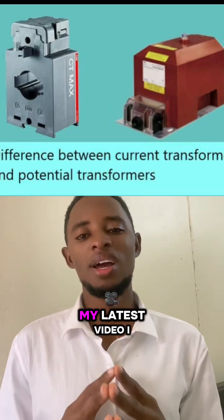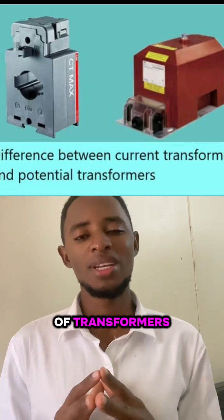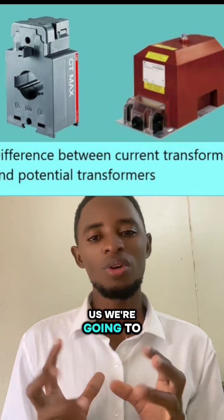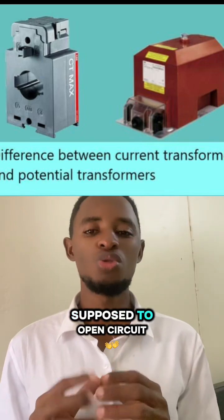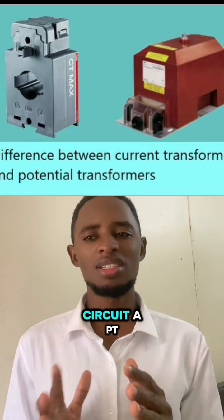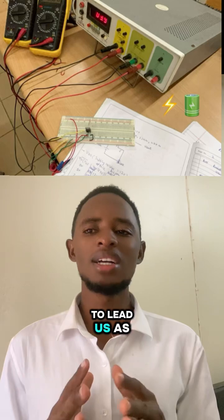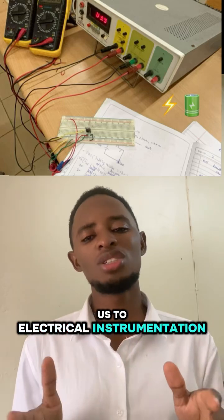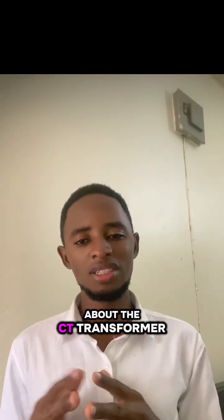As I said earlier in my latest video, we are going to talk about the special types of transformers, that is to say the CT and the PT. We're going to talk about the special rule and why you are never supposed to open circuit a CT and never short circuit a PT transformer while it's operating. This leads us to electrical instrumentation and measurements. As of now, we're going to talk about the CT transformer.